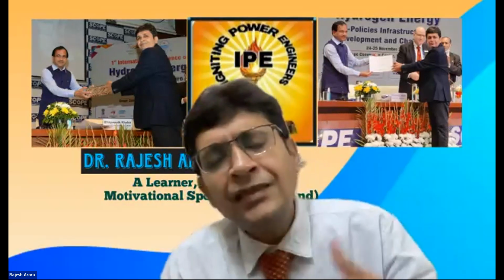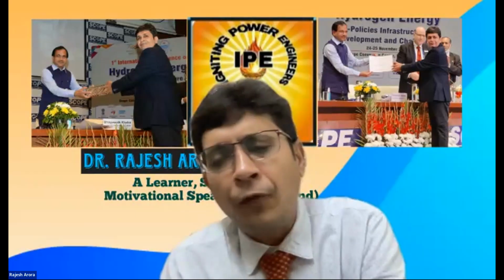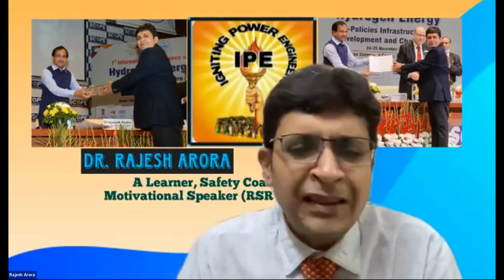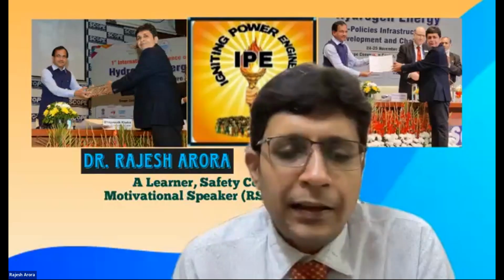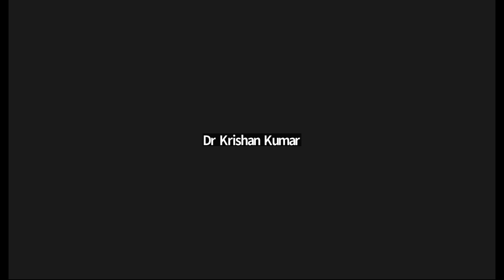The fault happens when the fault starts from the source up to the point of fault. So many impedances are coming in the series, and in no case can it go up to 600 kiloampere in the present scenario. Exactly, sir. Because it's coming beyond the lightning current itself, sir. Right. So the data was not correct. It is a base MVA value, I think. Okay.